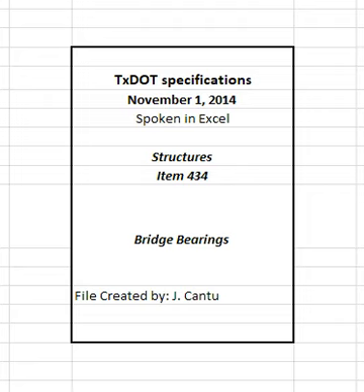Exercise care in any field welding required for the installation of a sliding elastomeric bearing to prevent damage to the elastomer, PTFE, or stainless steel surface. Repair damage to protective coating on the bearings and apply the final appearance coat in accordance with Item 446, Field Cleaning and Painting Steel. Damaged bearings will be subject to rejection and require replacement as directed.